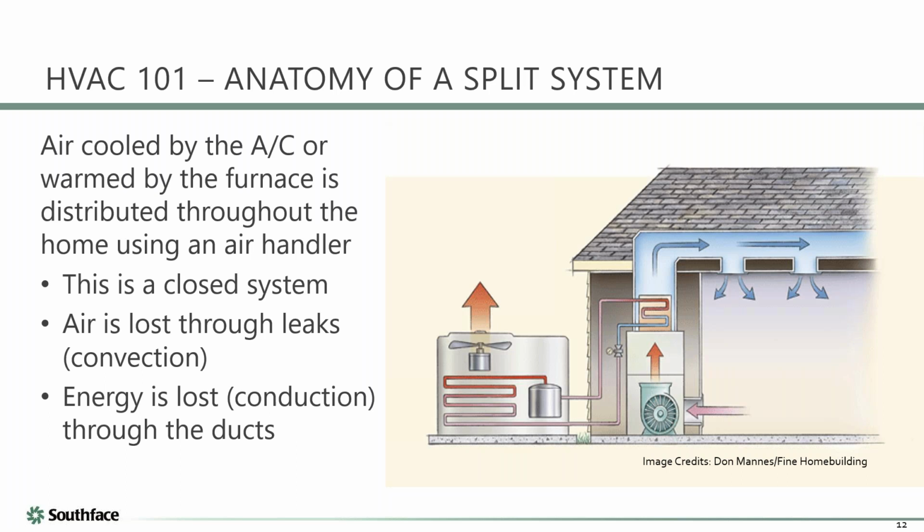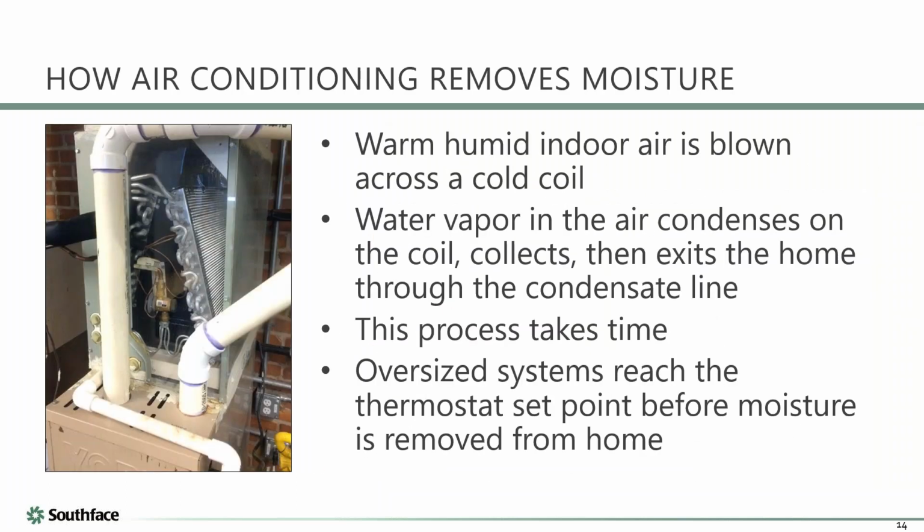I don't know if I rambled on too much with that one, but if people ask me today what features I want, it's like, yeah, you want variable speed. And that's why mini splits typically perform really well, because they're almost always inverter driven and can vary their load. The idea is to run a lot, but on low speed. You get good moisture control.